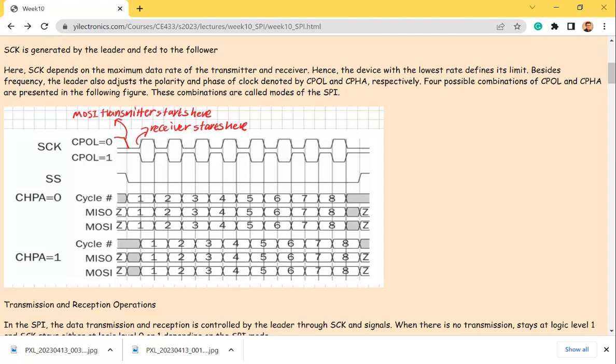I made a wrong statement. It's not a 2-layer board. You know why? If you flip it, look at the back. Did you see the little tiny holes? Yeah, a few very tiny holes. Did you see the 2103? Did you see that number? Did you see the very small holes? It's not a through hole, but it's a hole. The holes are not through holes, which means they are not 2-layer boards. The holes get into the intermediate layer somewhere.